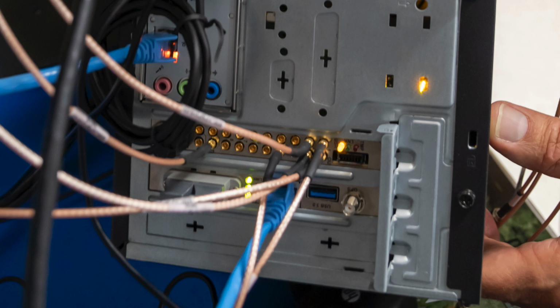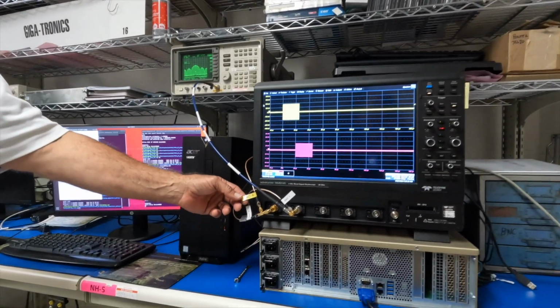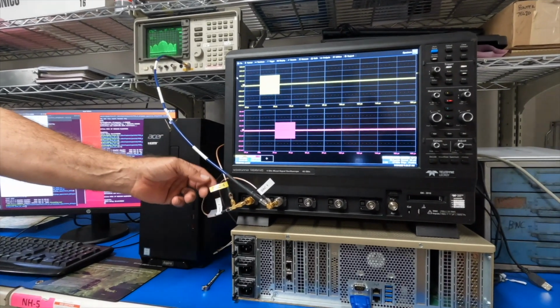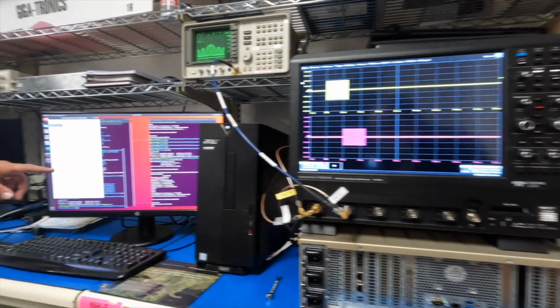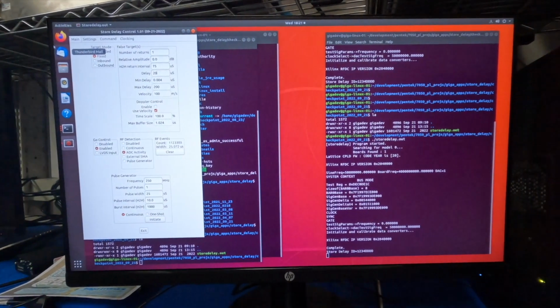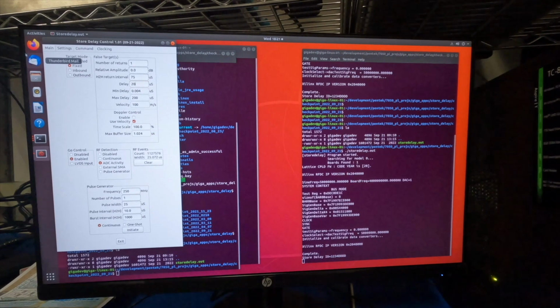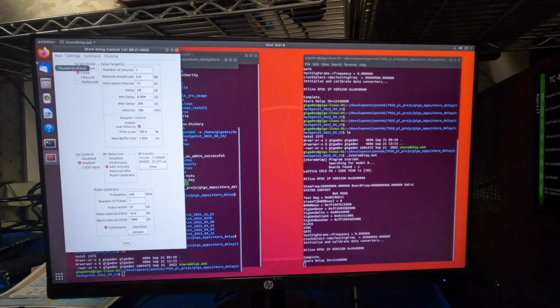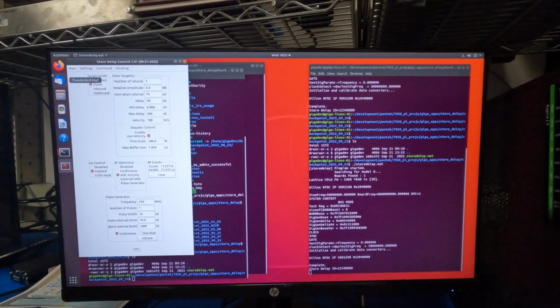The 4th of the 8 outputs of the DAC, the digital analog converter card, is generating a signal based on software we have. The software is controlling the RF SoC card, controlling one DAC, and we have a preset setting for a pulse train and a pulse waveform that we're going to use to input to the DRFM.